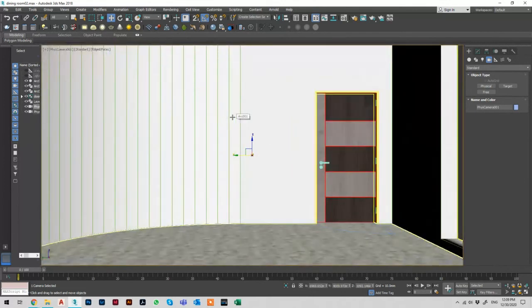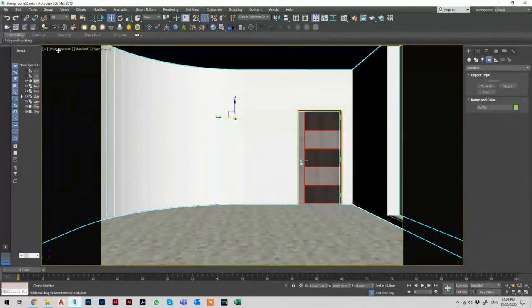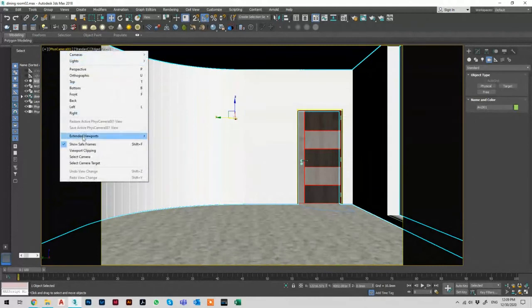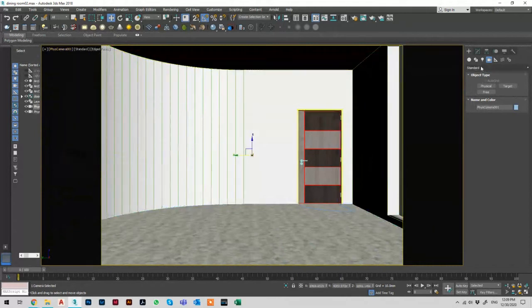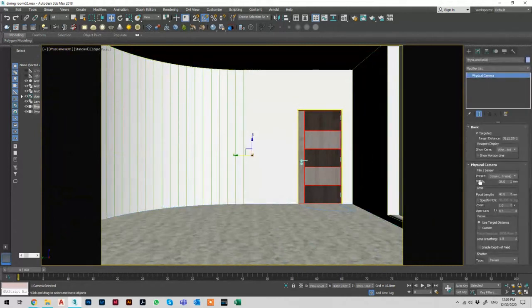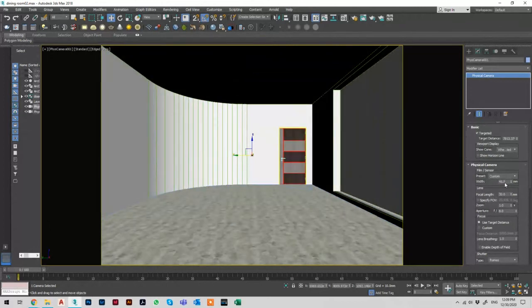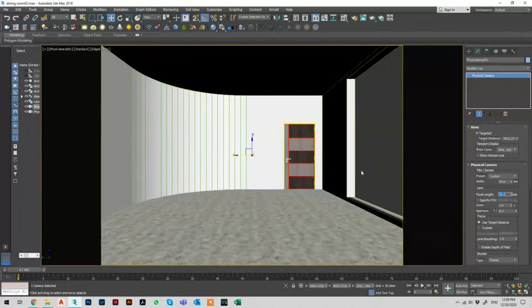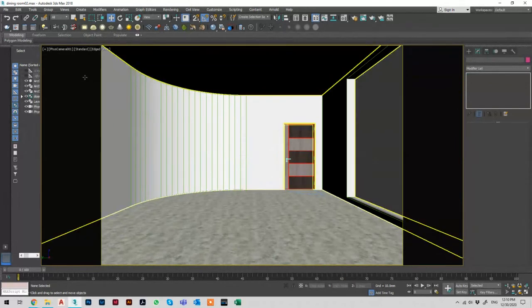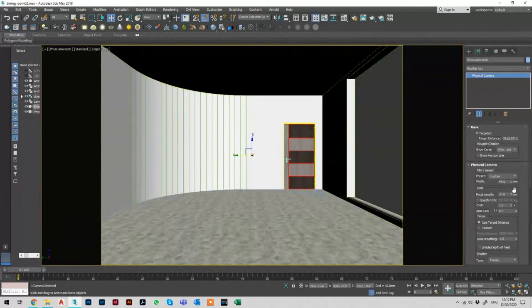And you will see here that you have the Z axis, so whenever you're going up or down, you can see your view. Make sure that you have your same frame on, and then go to the camera settings so you can select the camera from here instead of going to the top view and selecting the camera. So select camera, go to modify and change the settings. So we have the width here for the camera, the film width. You can change it to, for example, 45, focal length to 30. These are all in millimeters. Okay, so this will give you a bit realistic view. Sorry, 35. Realistic view of if you were in the site itself or if you're in the space itself, how you can view the space.